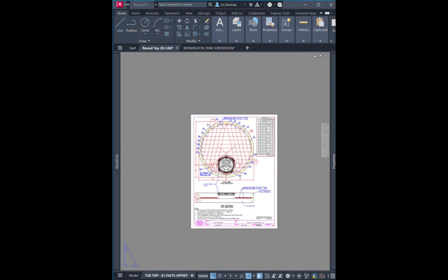Okay, and just make sure you select the table, go to the properties and change it to high resolution. So when you select the table and go to the properties, you will see an option at the bottom: monochrome, high resolution or low resolution. So you'll select high resolution, because if you select monochrome or if you don't change it, the table will be printed in black, and we don't want to do that.